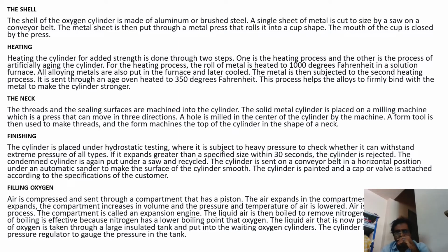When the air expands, the compartment increases its volume, and the pressure and temperature of the air are lowered. So whenever there is an increase of volume, the temperature of the air is lowered, right? It's a kind of Boyle's law. So air is liquefied by this process, and the compartment is called an expansion engine.